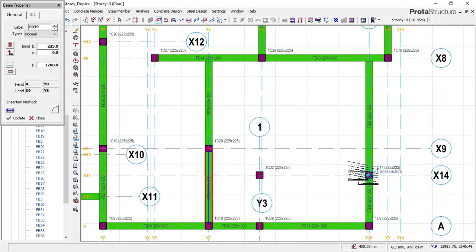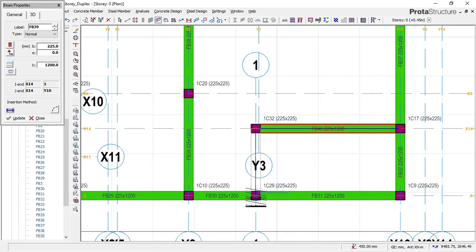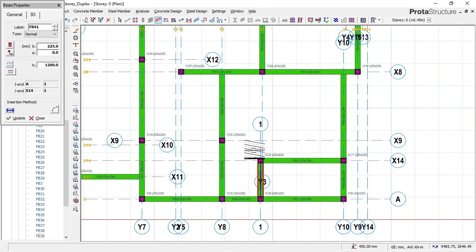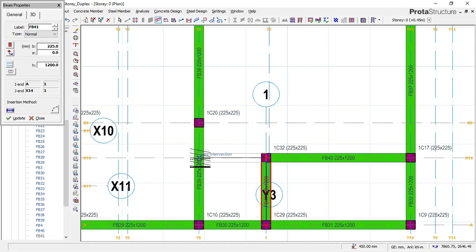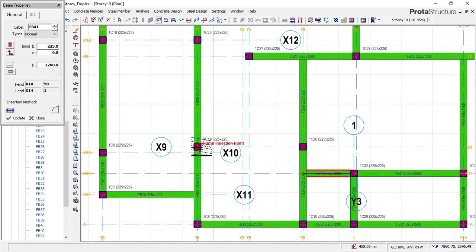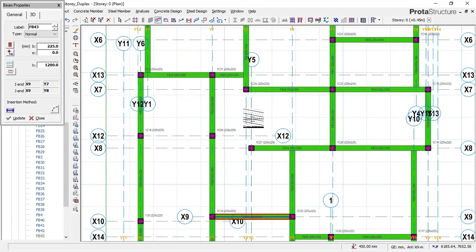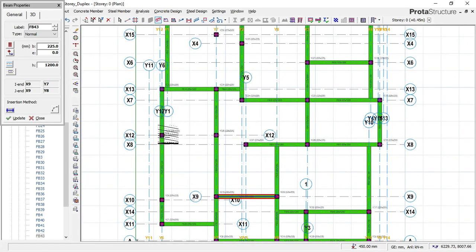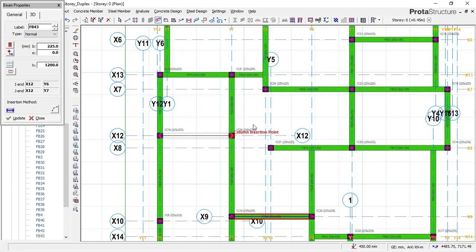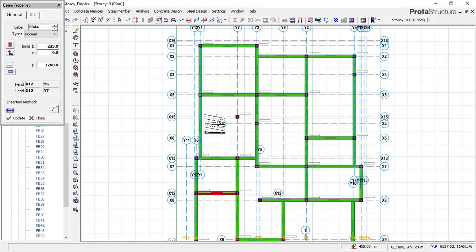So I'll do the same thing here and then cover up here, and cover up here. Now I'll close up this place here. Here becomes a panel. Okay, that's nice. Now your beam arrangement, your ground beam arrangement on this place, lies on your hands, as the structural engineer. So you have to determine the direction you want your ground beam to run. Let me go and check how I did my beam insertion in this area.